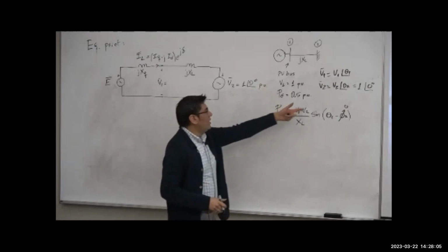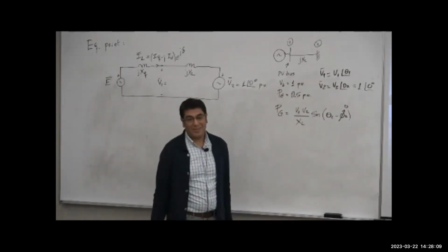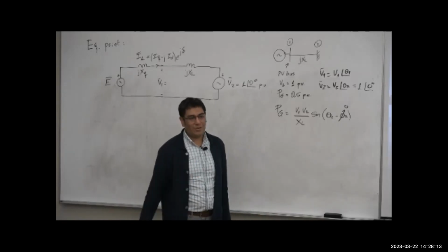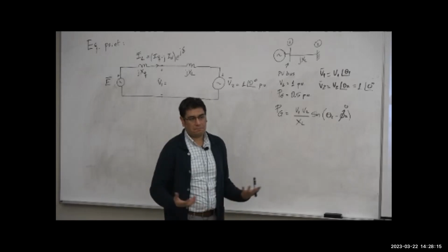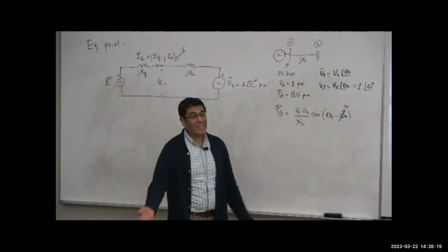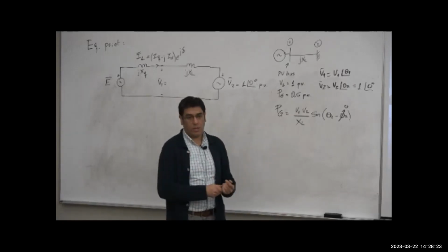If we don't realize that that's the way to do it, what would be the procedure? A power flow equation, right? And what do you need to do? It's a PV bus. We need to iterate. What technique are we going to use? Newton-Raphson. We like Newton-Raphson.